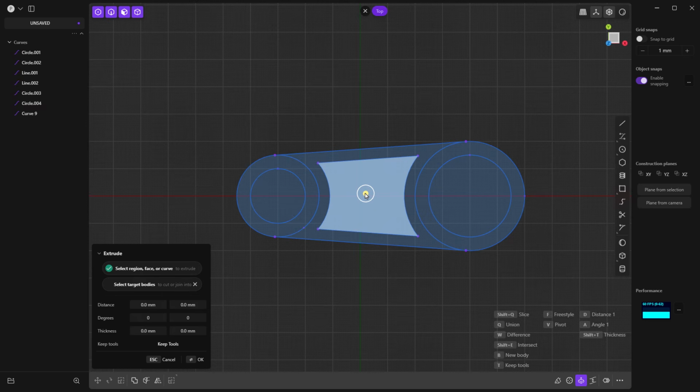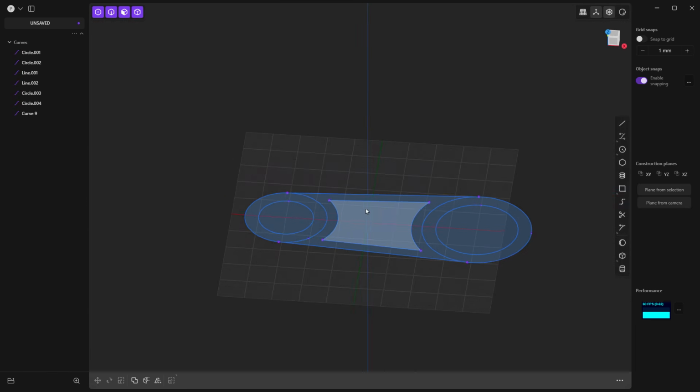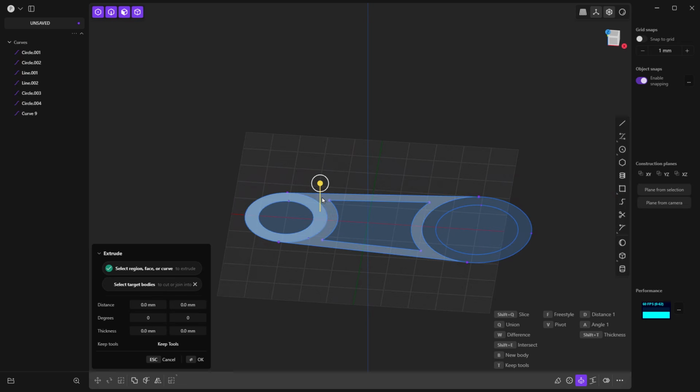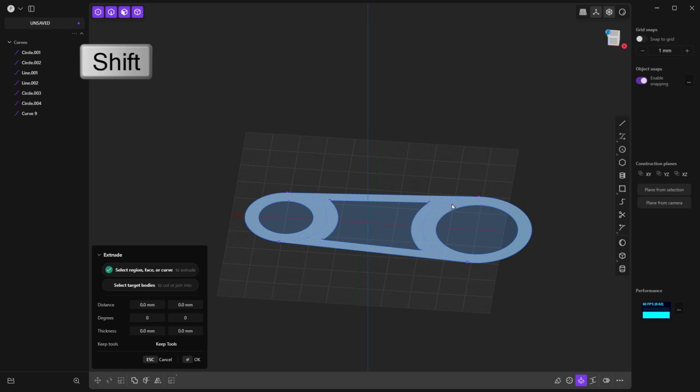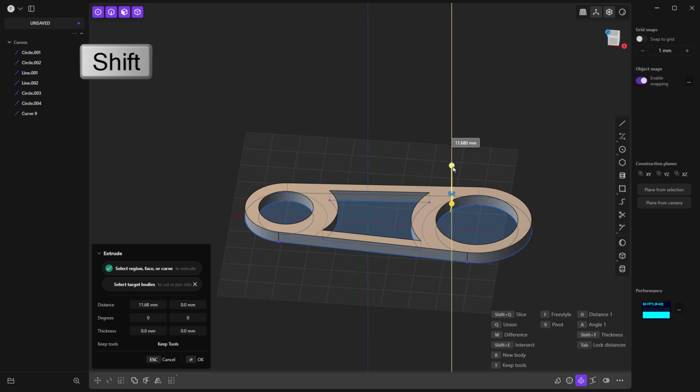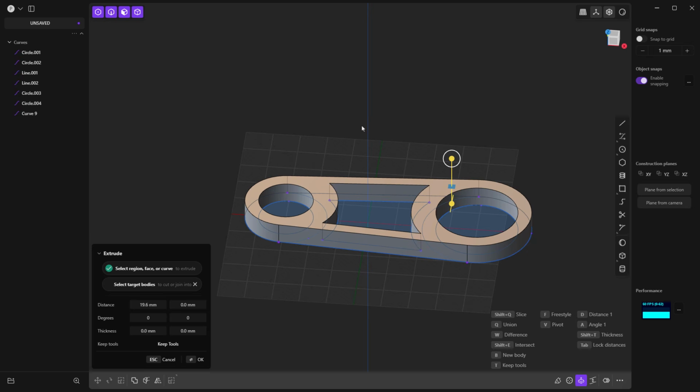So this is going to allow us to create an opening in the center of our link as we cut through. So we pretty much have all the geometry we need. We can go ahead and rotate and then begin pulling this up. I'm going to hold down the Shift key and select these 3 regions and then begin extruding this up.